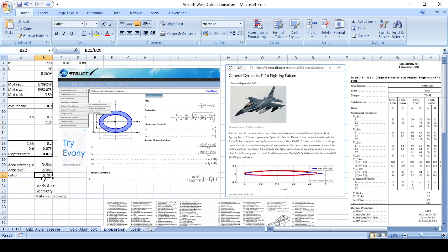And there's a reason why I did that, because I'm going to calculate the area of my spars, which are spread around that, and they're just similar single rectangles. So I'm going to scale my spar areas by this 0.785, and then my moment of inertia. I've also calculated a moment of inertia ratio of about 0.59. If I calculate that section as a rectangle with the same height and depth, and then I calculate this oval, then it's about 0.59. That's just to simplify that. If I assume that was a rectangle, then I just need to factor the I by 0.59 and then the area by 0.785, and I've got the properties of my aerofoil.